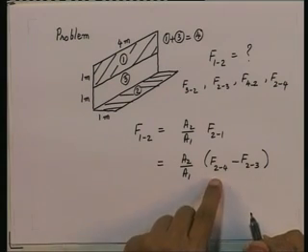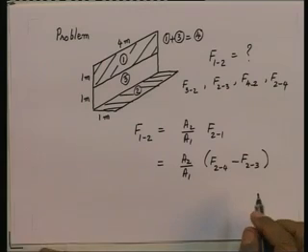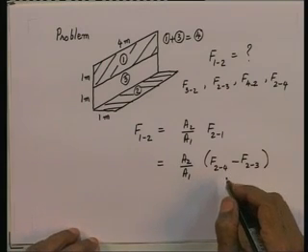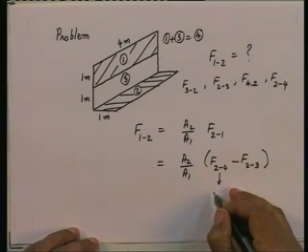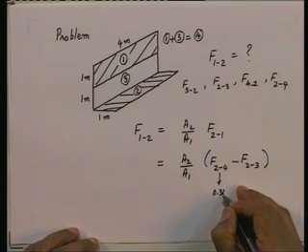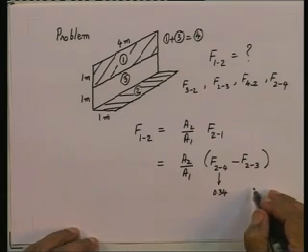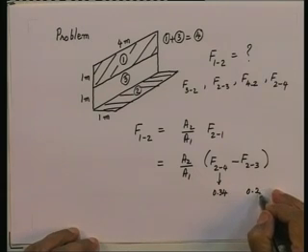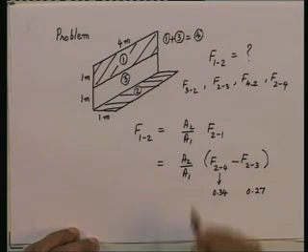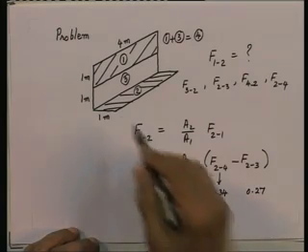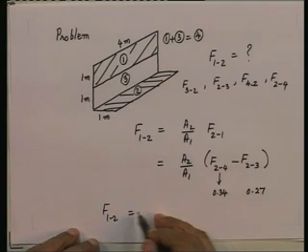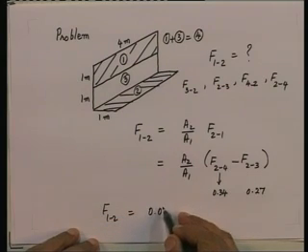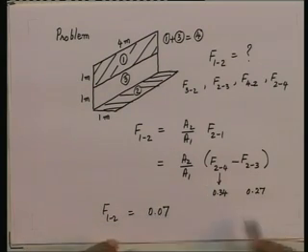So, read off these two values for this case. I am telling you, if you read them off, you will get the first one to be 0.34, the second one will come out to be 0.27, all right, and a2 by a1 is obviously 1 in this case. So, you will get f1 to 2 is equal to 0.07.